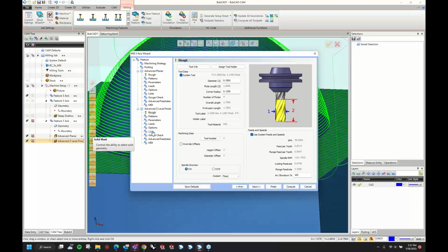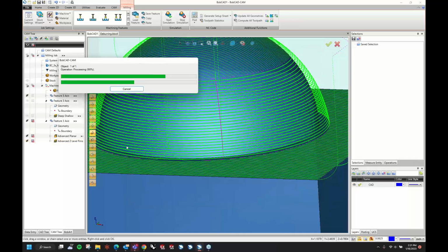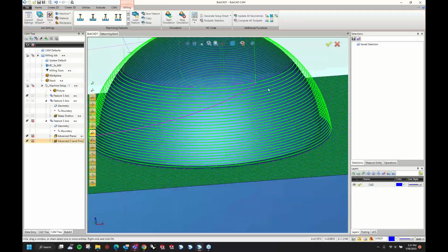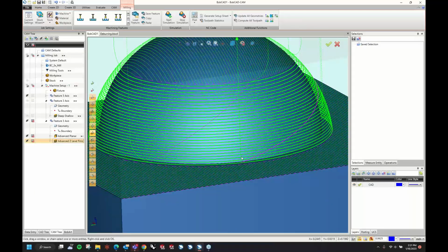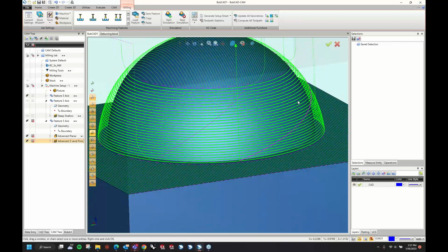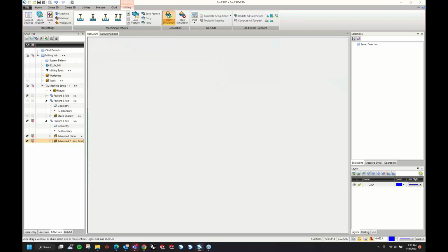I can do the same thing, but I have to go in and tell it the linking position shifts, say 100 thousandths per depth. So now that link is actually adjusted, but I can't adjust this one. I can only adjust this one. So even though it's a really fast, easy toolpath, you get a lot more flexibility of separating them out.